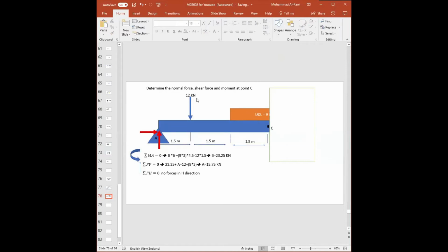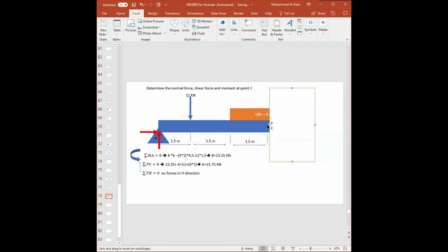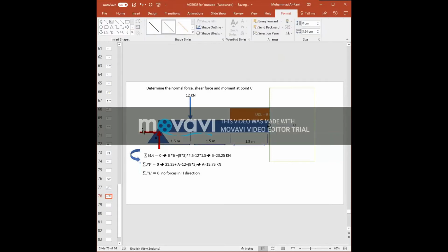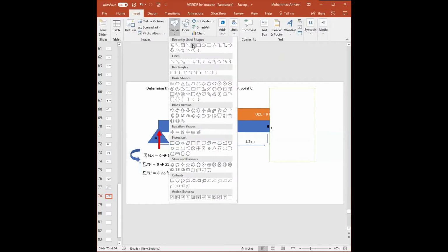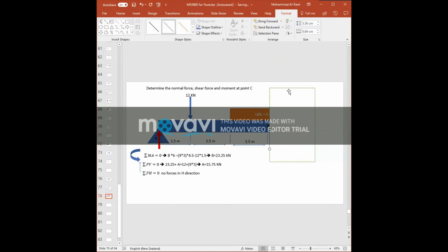Now, when I cut the geometry, what I always do is replace that by forces and moments. So usually, technically, we should have a force in that direction to support what? The one in red, that direction. But because, as we said, this force doesn't exist, this force doesn't exist as well, because they are equal to 0. There are no values for them. So now which force do I have? I have a shear force, which is of the cut in that direction. I will just highlight it so you can see it, guys.